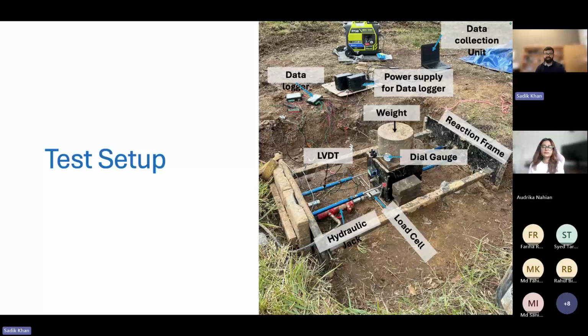So we wanted to make sure that we are primarily creating shear here, not any kind of torsion. That's why we used 4 LVDTs to look into that, and then we try to control that when we are loading it or failing it.